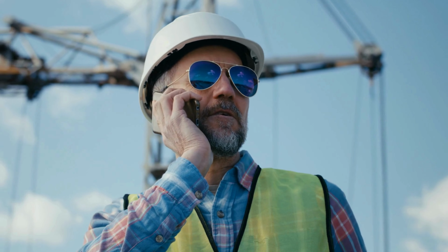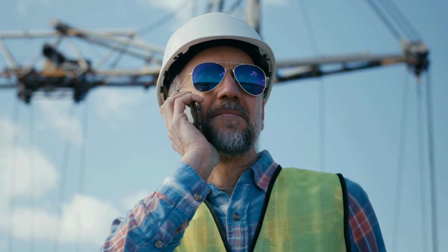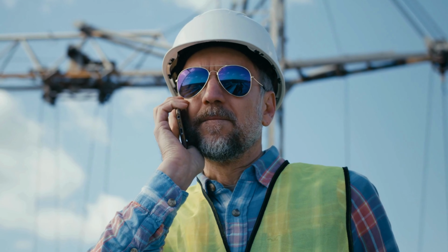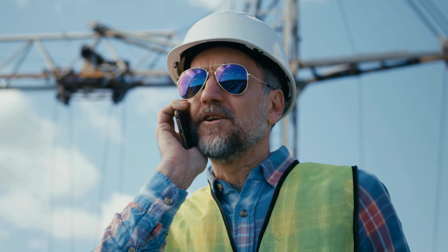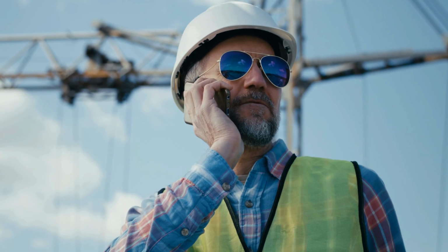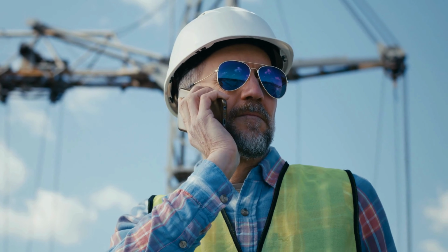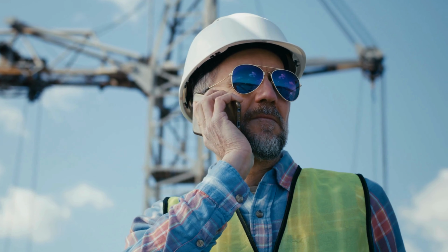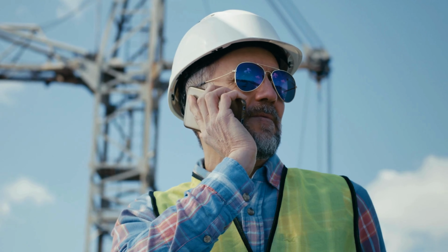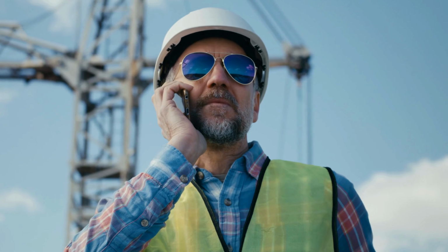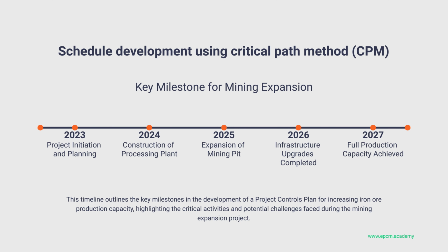What about the cost side of things? How do they go about estimating the costs for a project of this scale? They'll need to use a combination of techniques, things like parametric estimating, which uses historical data to develop cost models, or detailed quantity takeoffs, where they actually measure and calculate the quantities of materials needed. The key is to consider all the relevant factors: market prices for commodities, regional labor rates, and those often significant transportation costs for getting everything to this remote site.